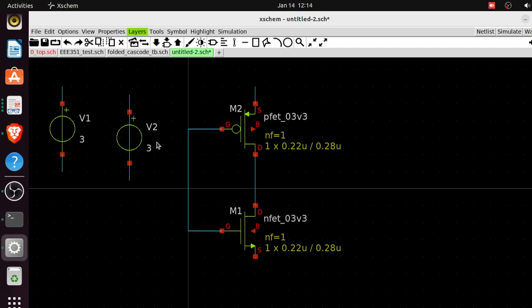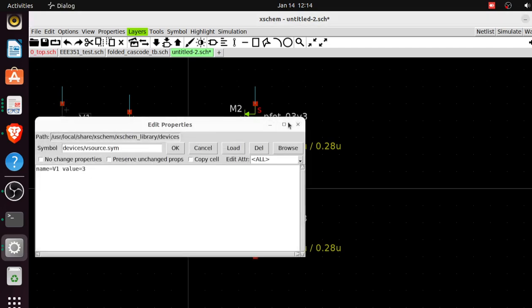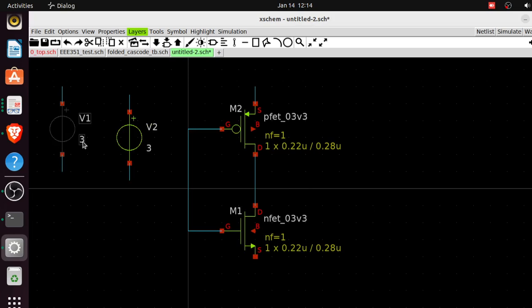Okay, so all I just do now, since electrically I want this node, this will be VDD, right? VDD should be 3.3 volts because for GlobalFoundries, the voltage for the process is 3.3, so you get a max of that.